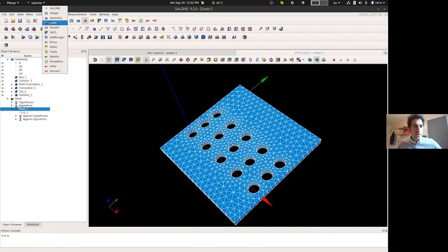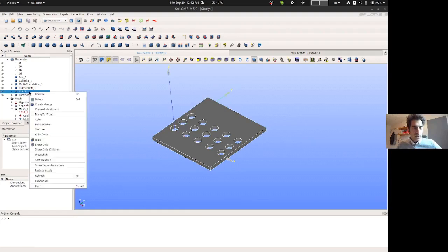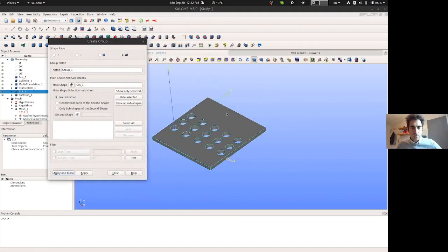So now we can go back to geometry and say, look, I want to have some surfaces clamped, and one surface where loading is put on it. In order to do this, I'm going to go to this cut geometry, make a right click and create groups. Okay, so one group will be the domain, the 3-dimensional. I have only one single material, so it doesn't mean a lot, but still I'm going to do it. I'm selecting it and then adding it. There's a number which I don't care about, so I'm just giving it a name. I'm going to say continuum body.